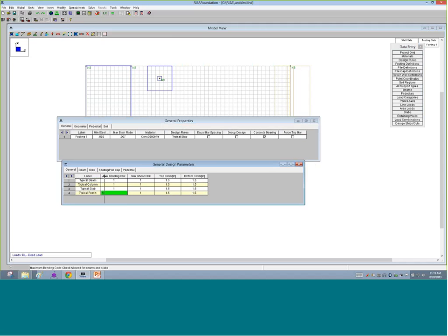And we'll see the program will tell you here it gives us the maximum bending check and the maximum shear checks, and that means that if you don't want to run to the 100% of the capacity for your steel there, maybe what you do is you tell the program 0.9. I want to go to 0.9 for my max bending check and 0.9 for my max shear check.